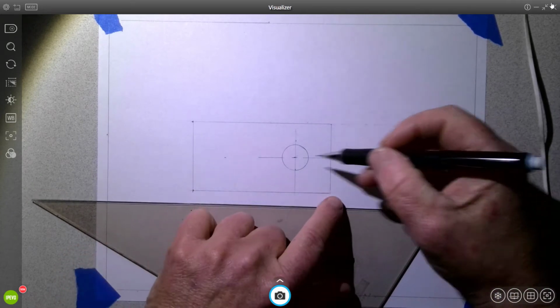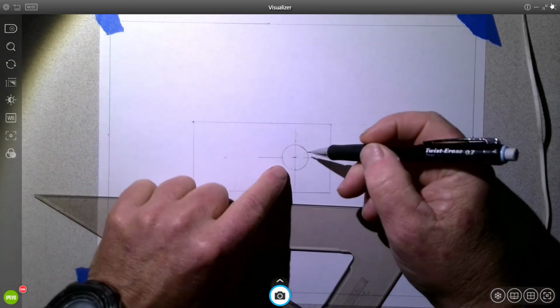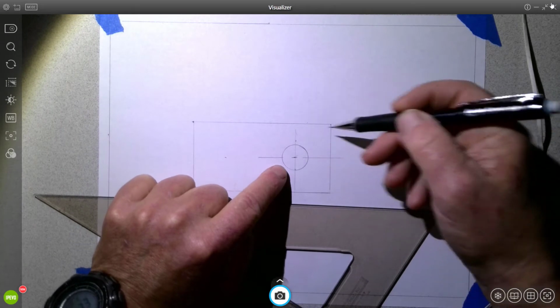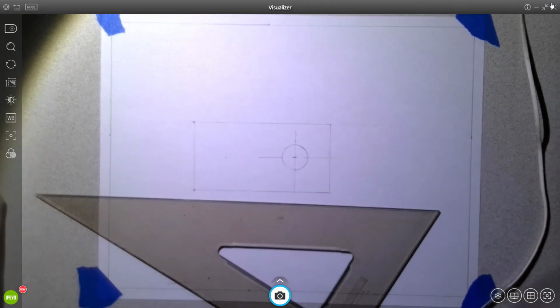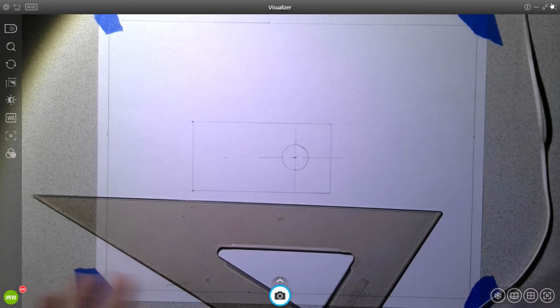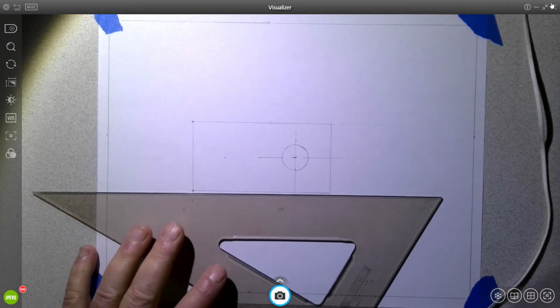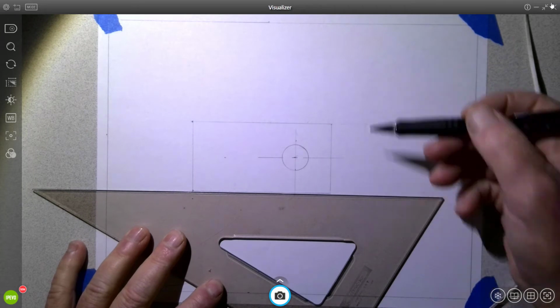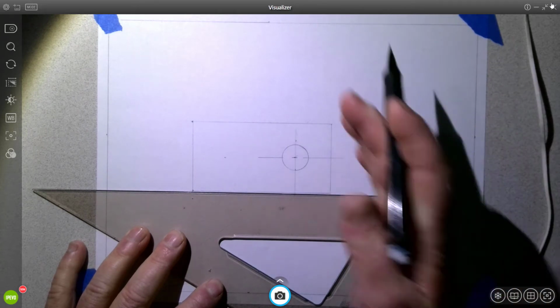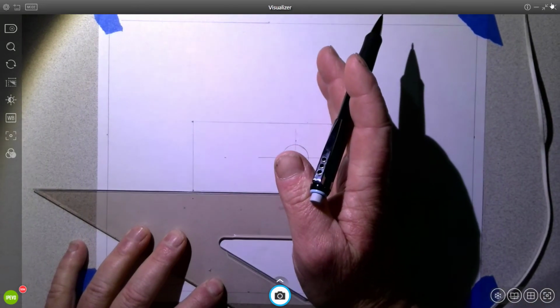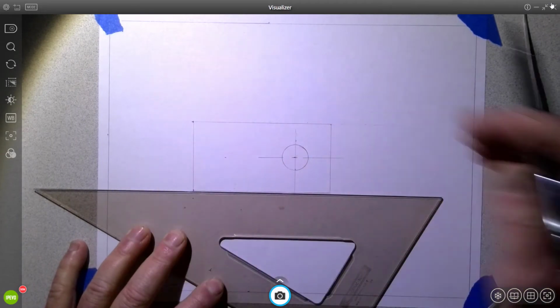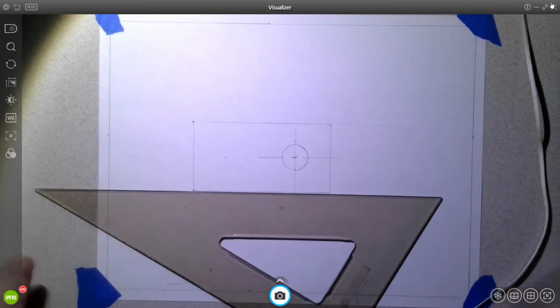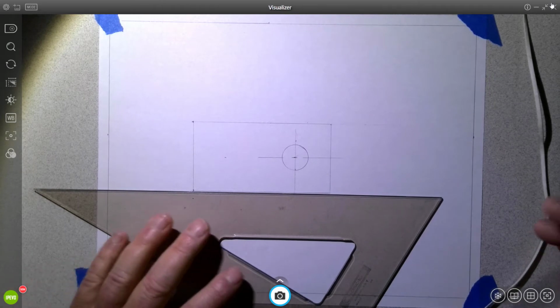All right, so now for dimensioning, let me just go through it again. Let's say I want to locate this hole. So a full position location is going to have both an X and a Y dimension. That's how you locate it. There's a number of strategies to this. Something called baseline, which means maybe this bottom is the base and everything should get pulled off the bottom. And maybe the right edge is the vertical base and everything should get pulled off the right edge. That's a little beyond the scope of what we're doing, but there are concepts there.